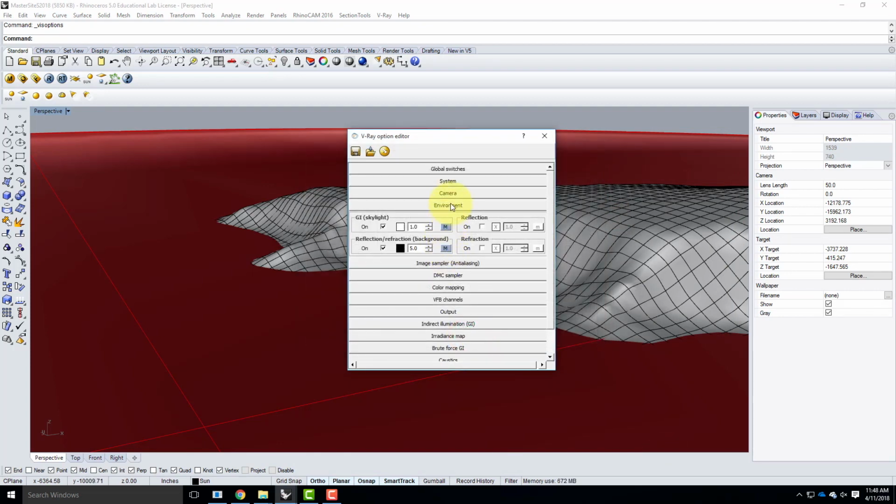So theoretically, at this point, all of my V-Ray settings are correct. I've loaded my HDRIs. I have my sun. Everything should be good for the render. If you're doing the Lake Tahoe scene, the only difference is you probably won't pick the Malibu HDRI, but any of the other ones tend to work fine. And I can help you through that if you get stuck. It's always hard because I'm demoing one versus the other, but they'll end up working out in the long run.